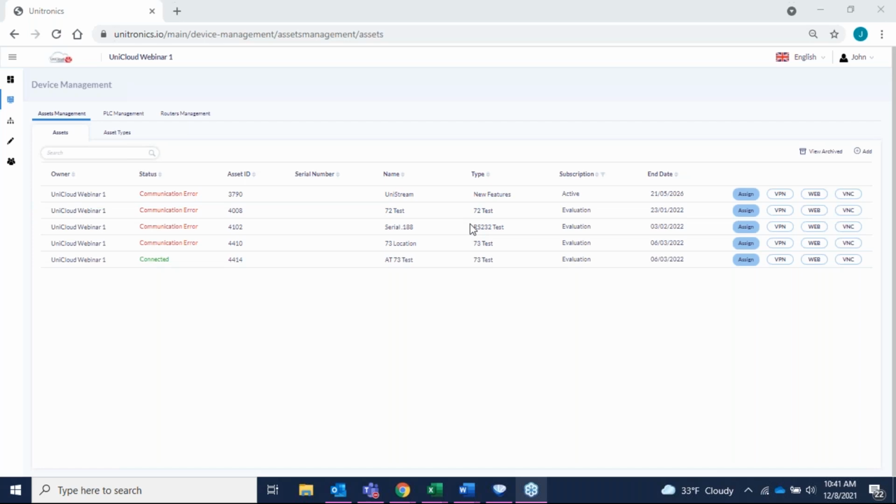Now, you can allow users to do this, or you can block users from doing this. But if you are allowing them the capability, this is independent of the update rate that you have for your subscription. If you are writing to the controller, the second you press enter, that value is going to update in the controller. So be mindful of that, right? That can be very helpful in some scenarios, but detrimental in other scenarios.